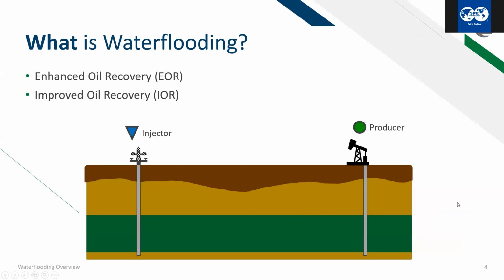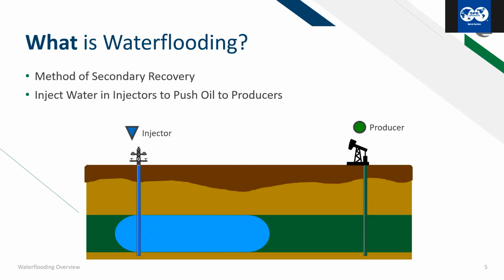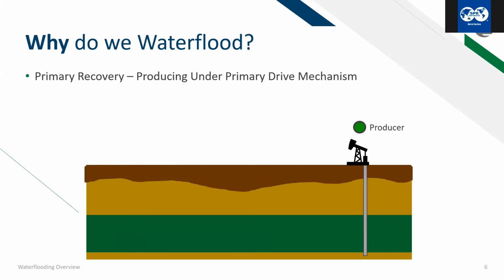So what is water flooding? It's generally referred to as enhanced oil recovery or improved oil recovery. And it's defined as a method of secondary recovery, which means that you inject water into injectors and you push oil to producers. Mechanically, that's what a water flood is. But to really understand water flooding, I think you need to ask a different question. Instead of what is water flooding, why do we water flood? Right? Because it's not just to get oil out of the ground.